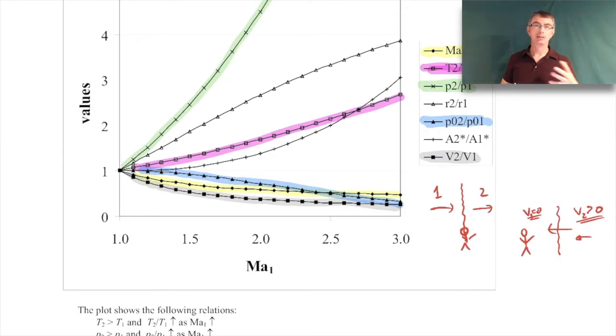So this is why when they design aircraft engines and things like that, it's better to isentropically decelerate a flow, to slow the flow down in an isentropic manner so you maintain the stagnation pressure, rather than go through a shock wave. So like when you have flow going into a jet engine, generally you don't want that flow to be at supersonic speeds. Because you can get the possibility of shock waves and things like that that can cause damage to parts in the jet engine.